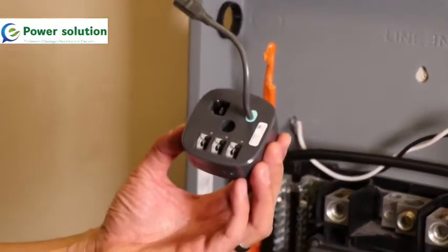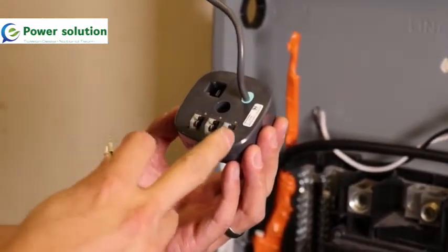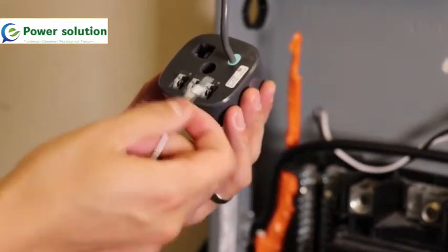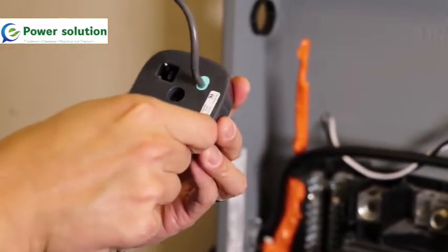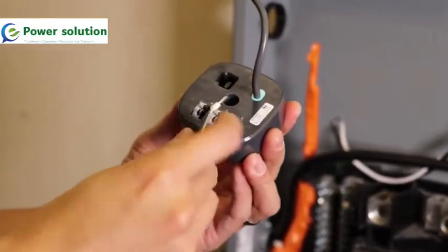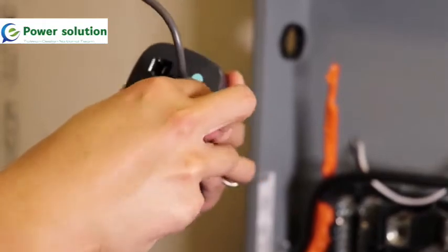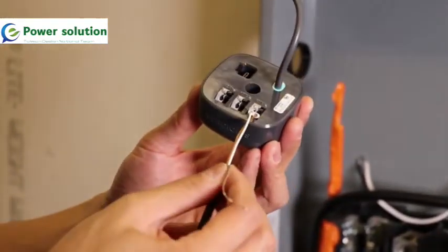When connecting an off-the-shelf CT to the generic interface module, you'll select one port for each CT. Make sure the darker wire of the connection goes into the darker socket, and the lighter wire goes into the lighter socket. For the purposes of the Rogowski coil, there's a shielding wire that you do not need to connect.